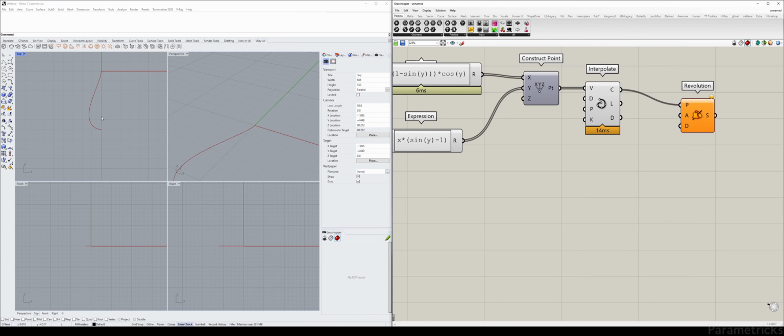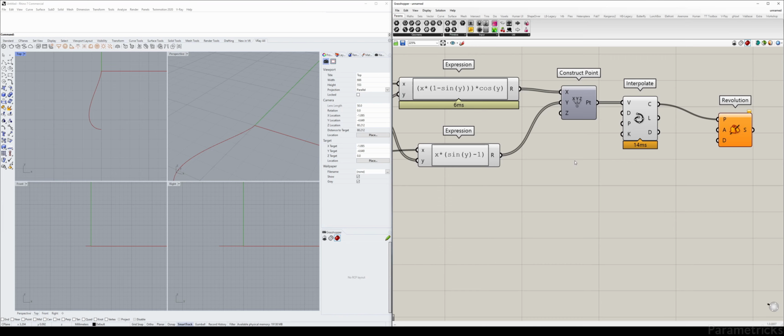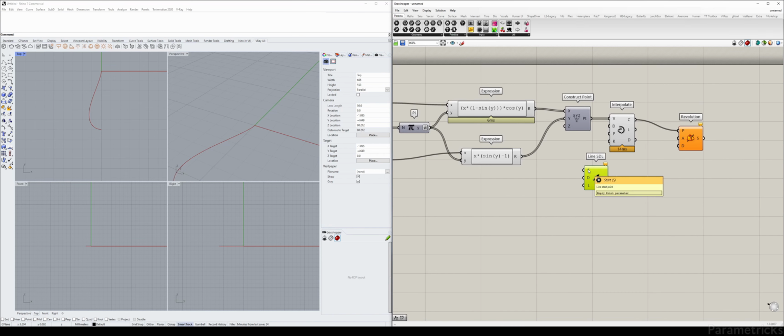All right, so we have the A, which is the axis. Obviously, we want the middle axis, which is going to be Y. So to create an axis, we're going to create a line. We're going to create a vertical, an SDL line. So this one takes in a point, direction, and the length. The length doesn't really matter. So we just need the S and the D input.